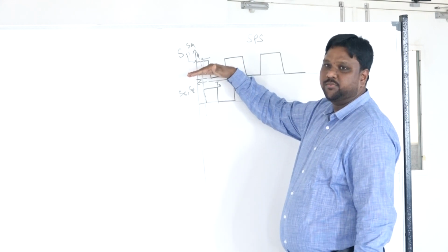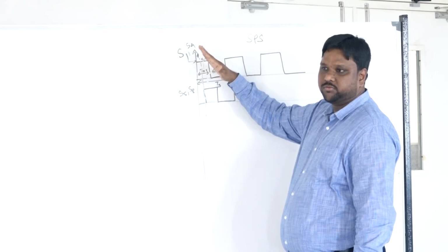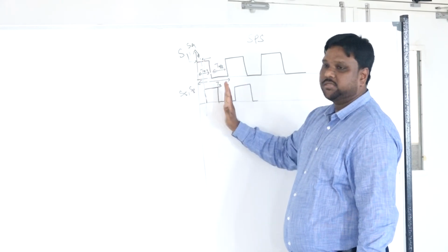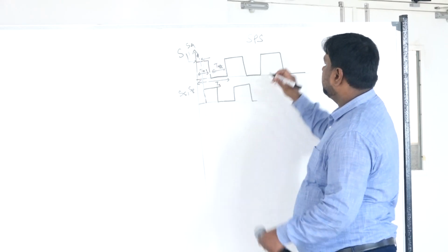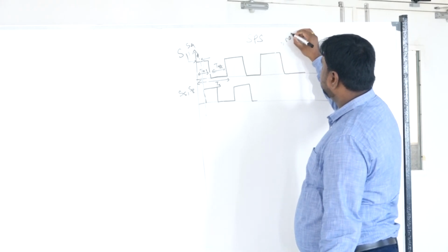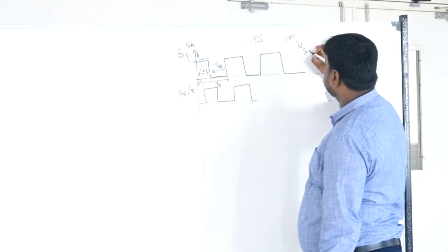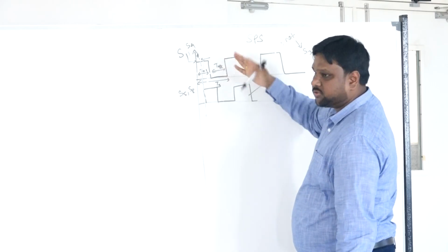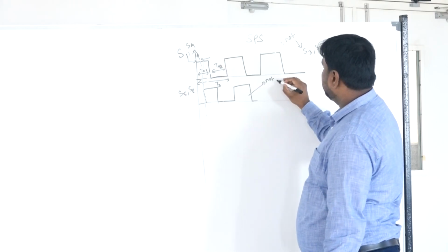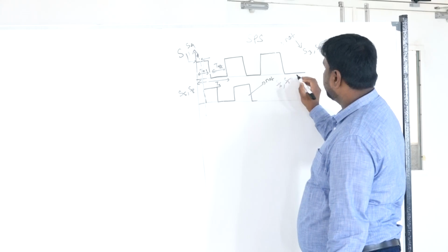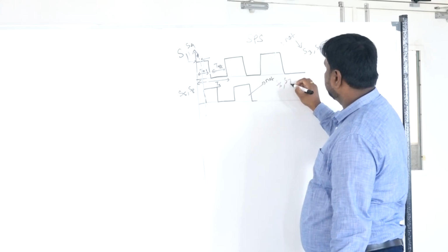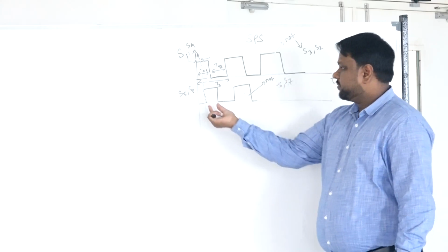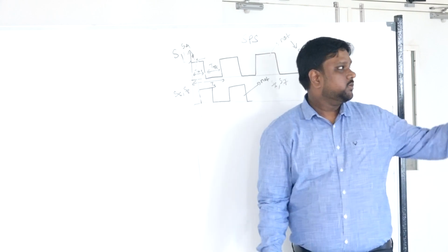We are keeping the primary train of pulses at zero phase shift and shifting the 5 and 8, and we can use a NOT gate here, and that will go to S3 S2, and here you can use a NOT gate. NOT gate means it will be inverted, right? It will go to S6 and S7. Okay. So that phi we are converting to time.